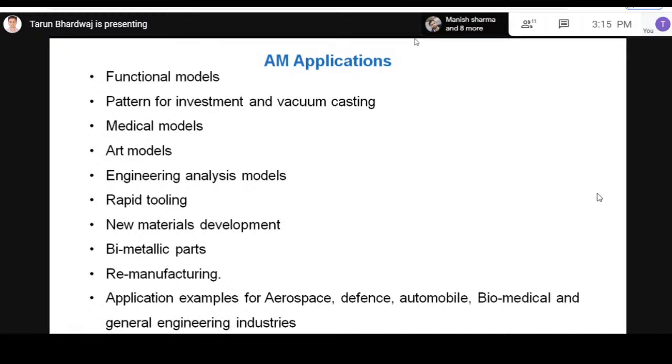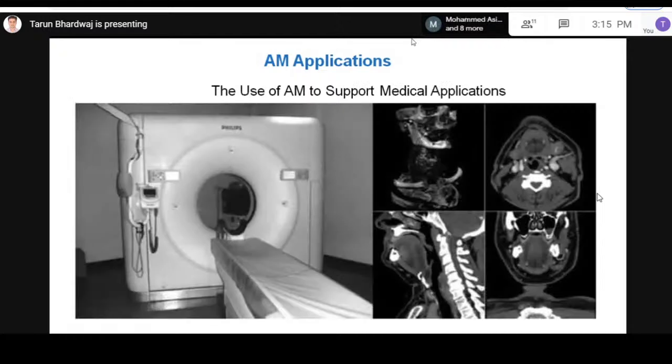And the shoe industry is also using the additive manufacturing process, because as you know, a shoe sole is quite heavy. If we require the same strength with reduced weight, we need lattice structures, or we have to create holes or intricate shapes in them. That is not possible by any process other than additive manufacturing. Adidas and Nike are using it nowadays to make their soles, and these are available in the market.